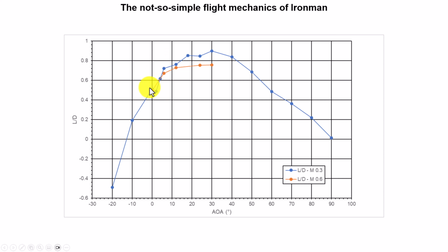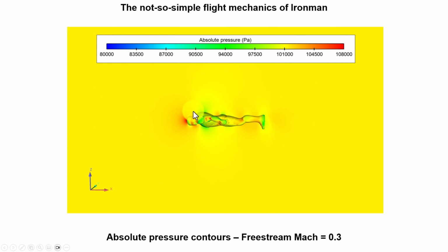Look at this red line, we have it at Mach 0.6. And here clearly you start to see those effects that I was mentioning, non-linearities. When you start to increase, I have already seen that at Mach 0.6 I have reached my critical Mach number. I have local regions where I have shock waves, and that will have an influence on my forces, and you see that it reduces. And it seems to get worse when you keep increasing the Mach number. So this is the summary, the results that we have.